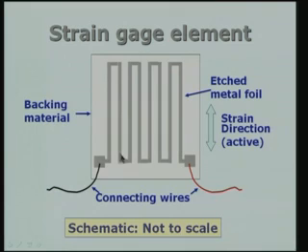In other words, to obtain a certain required resistance, we are going to have the deposited etched metal in the form of a length equal to L, which consists of these units. Each unit is something like one straight, one small bridge here, another straight. This is one unit. So, we have 4 such units here, and therefore, the length of this will be equal to 8 times the length of each one of the vertical units.